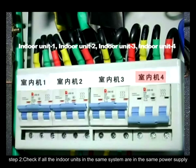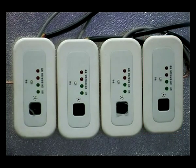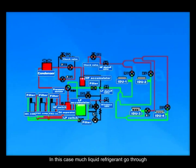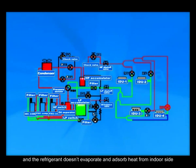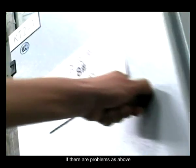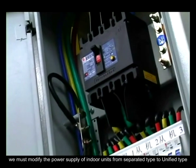Step 2. Check if all the indoor units in the same system are on the same power supply. If there are any indoor units without power, its electronic expansion valve keeps a certain opening degree. In this case, much liquid refrigerant goes through the electronic expansion valve of the indoor unit without power, and the refrigerant doesn't evaporate and absorb heat from the indoor side. So, the refrigerant goes back to the suction pipe of the outdoor unit in the same power supply. If there are problems as above, we must modify the power supply of indoor units from separate type to unified type.